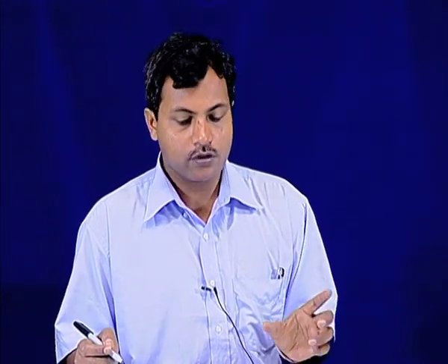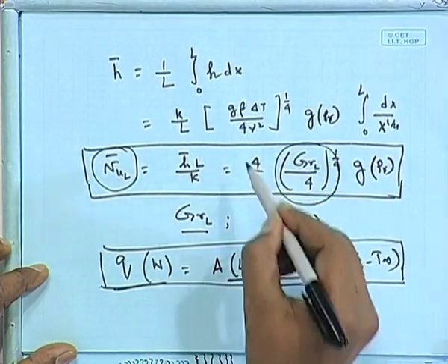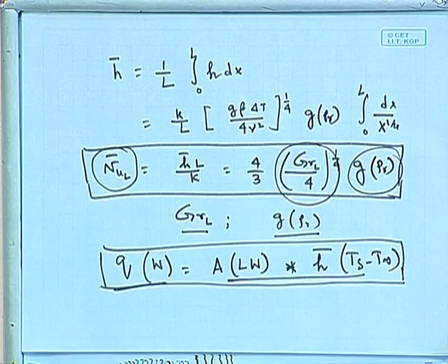So, again there are different formulations for those, but mostly once you know the form of variation of Nusselt number with the Grashof number and Prandtl number, the dominant non-dimensional numbers that are characteristic for your system, then you will be basically taking recourse to the various correlations, and you should know how these correlations should be used for the solution of a particular problem. So, in the next class we will be looking into those specialized cases and various correlations for estimating the heat transfer coefficient and how to apply them in certain examples.